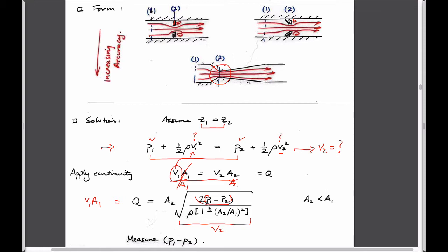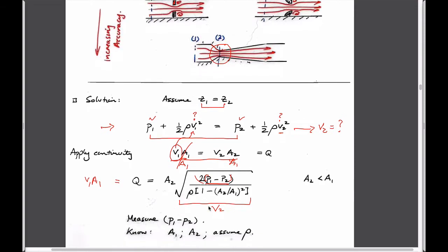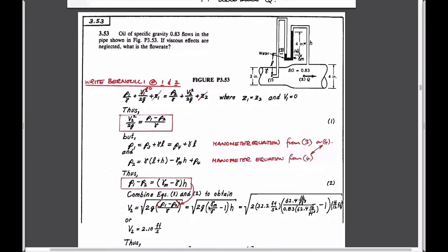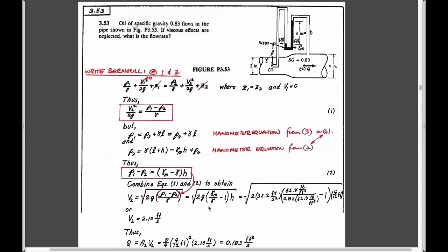It's only measuring the difference across the system. Pressure transducers always have ranges, and once you get above them, you blow it. If you're only measuring the differential pressure, then you can be anywhere in a much bigger range. And so that's the advantage of having a differential pressure transducer. So that's how an orifice meter works, or a Venturi gauge.